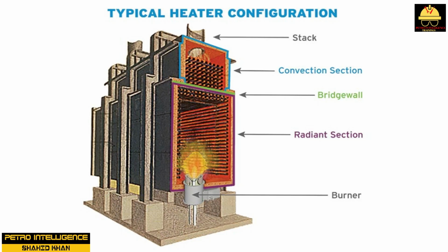The bridge wall section is the sloping section of the upper furnace that connects the radiant section to the convection section. It is designed to accelerate the flow of hot combustion gases out of the firebox and into the convection section and stack. The bridge wall is the wall that separates the various sections in the firebox. The heat-reflective materials in this area are designed to withstand temperatures between 1,600 degrees Fahrenheit or 871.1 degrees Celsius and 3,300 degrees Fahrenheit or 1815.55 degrees Celsius.